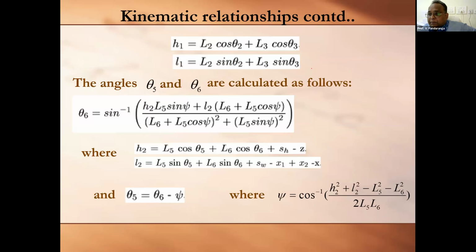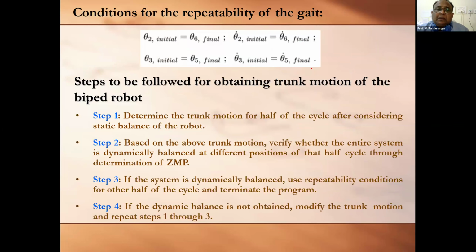So they are the equations that represent inverse kinematics, by following the geometry or trigonometry. And then we have followed some algorithm. Actually, there are 2 unknowns, theta 1 and theta 4, that need to be determined. So in this case, if you wanted to derive 2 unknowns simultaneously, we have to follow either the inverse dynamics approach or the semi-inverse approach, which is computationally expensive. So we thought of eliminating this inverse process and adopted a simple algorithm in a forward manner.